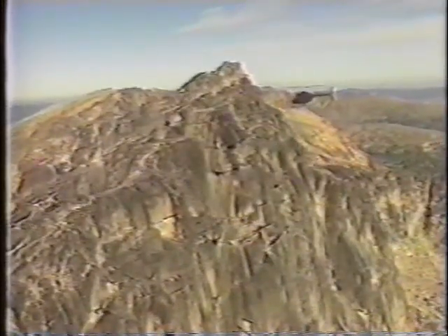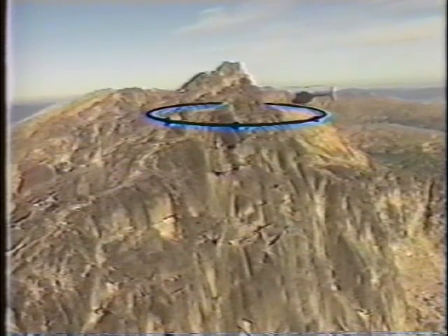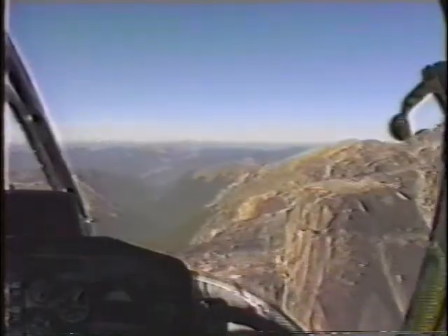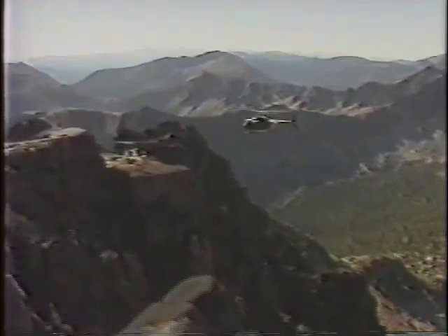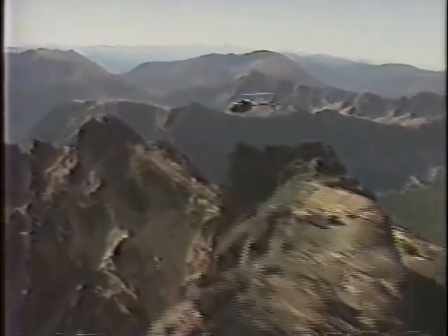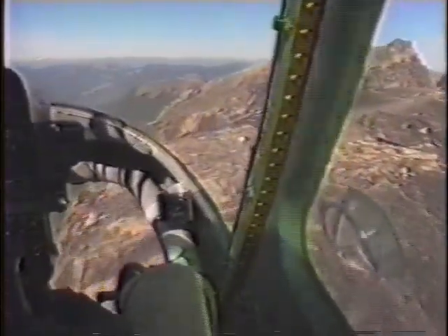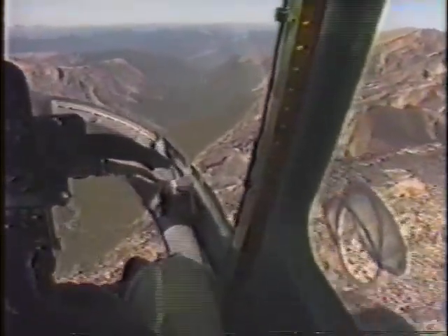Pinnacles can be treated similarly to crowns, but as we mentioned, they have a lot more turbulence associated with them. Do a circle recce until you pinpoint that unstable air, then switch to a figure 8. Downwind passes should bring you as much information as upwind ones. Try to stay clear of the demarcation line. It's very turbulent on a pinnacle. Use a steeper approach if you have to, and land on the upwind side to avoid backlash. Also remember, you're not going to get much ground effect. There's very little ground to get it from.